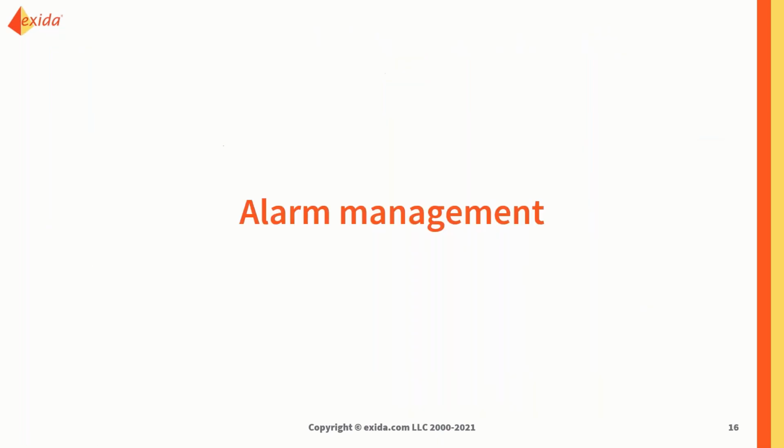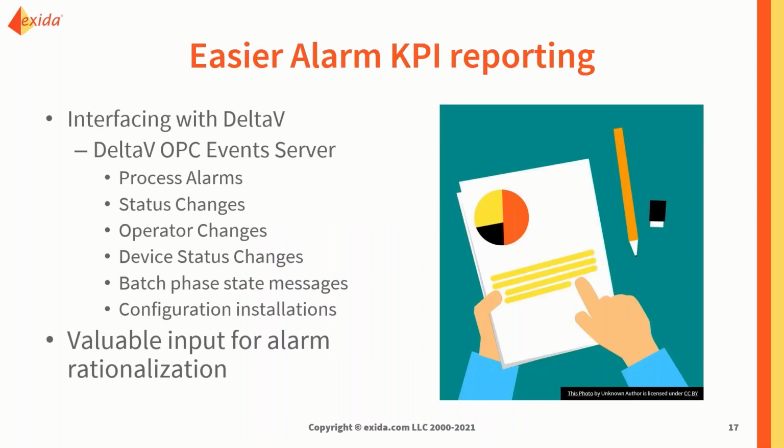For alarm management, we all know that it is for better managing your alarm system. In order to manage your alarm system, you need some kind of input, right? Already out there in the market, there are several tools developed by certain manufacturers that try to help with the process using OPC technology.